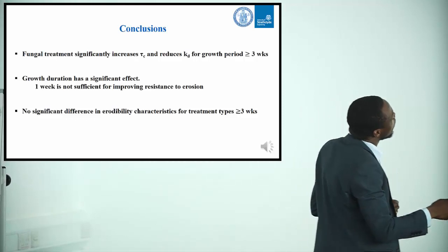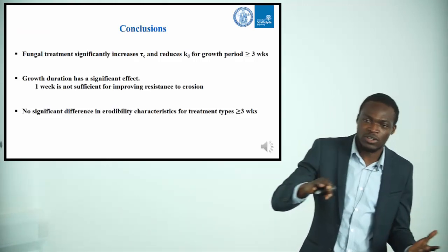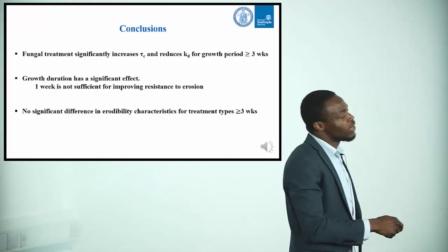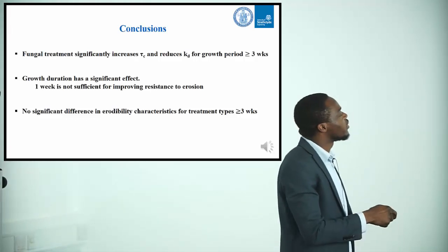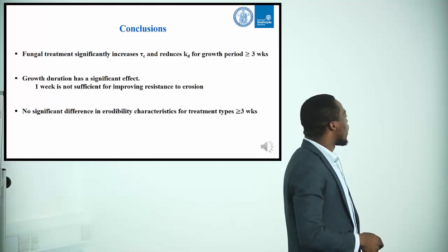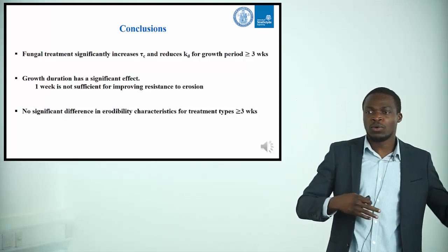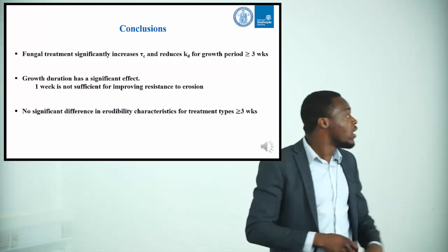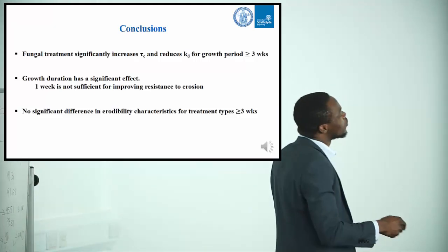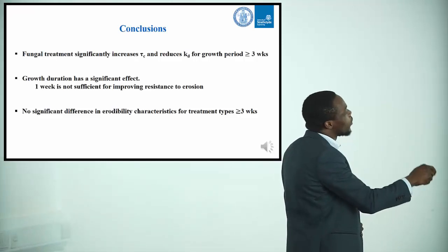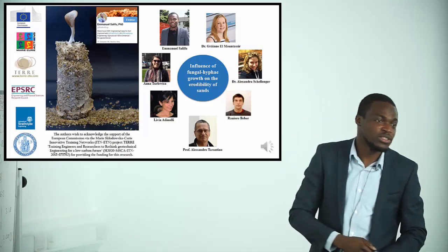Then we begin to infer that the water repellency may have resulted in incomplete saturation during the process of the test when it was submerged, and then there will be less infiltration and maybe higher suction in the treated soil compared to the untreated soil, and therefore helping to bind the particles together. Also, one significant contribution we have from this study is that typically soils that are water repellent, as induced now by this fungi, always lead to higher erodibility. They're usually loose and you have more erosion. But we have been able to show that sands that are water repellent by the growth of the fungi also lower the erodibility of the soil significantly.